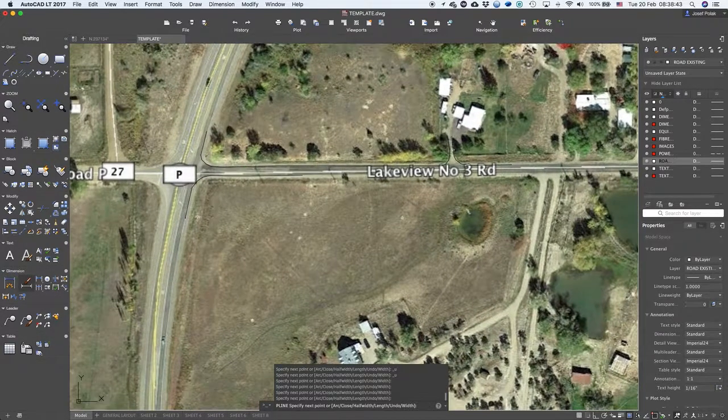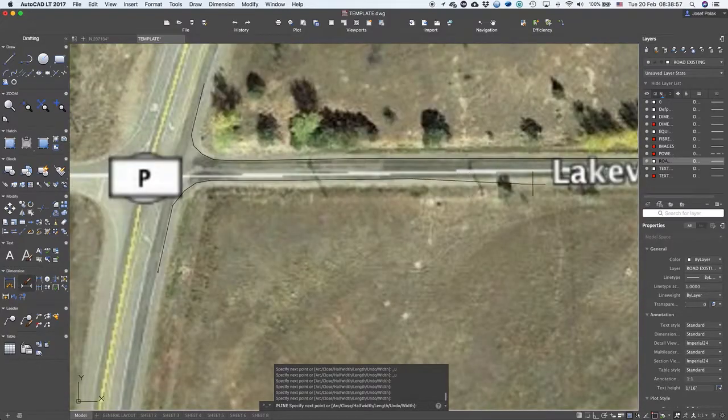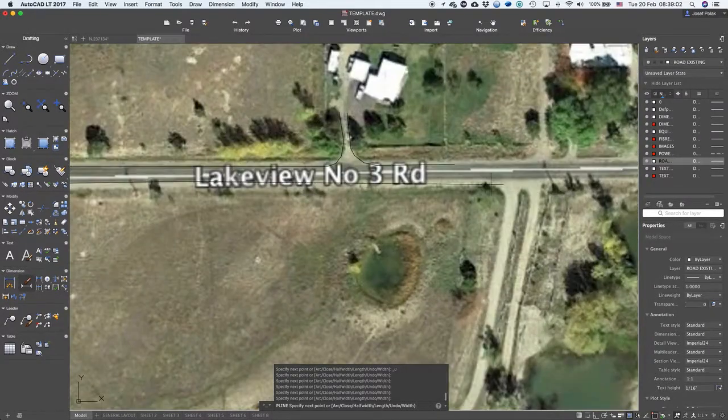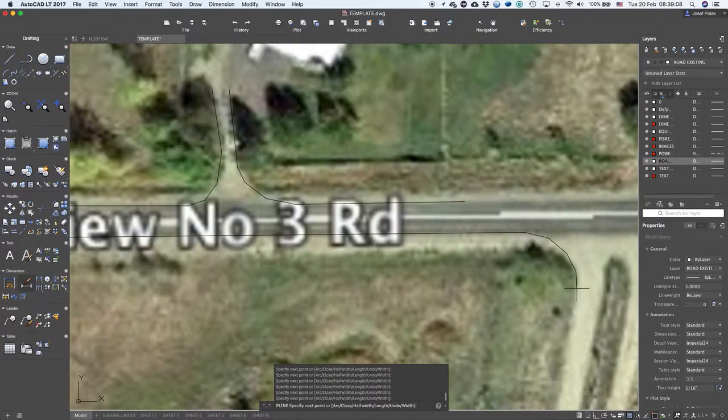If you're not sure where the road edge exactly is, I suggest if you look at the Street View, Google Street View, you can see if there is a road edge, because in this case it looks like road edge is here. Then we have some gravel area or just soil or stuff like that, which is already the place where we will install our fiber. We just won't install it in the asphalt road, right? So yeah, I'll just do this part.